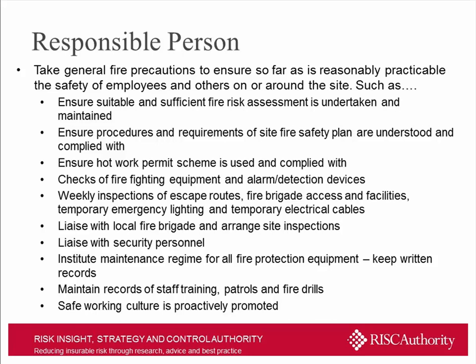One of the key outcomes of the fire that happened at Minster Court was that although the fire and rescue services arrived in very short order, with no delay in their being called and their arrival, what they found when they arrived was a fairly significant fire already, and really difficult access to any of the hydrant points that they needed, because they were within the hoarding of the building, and one or two of them were hidden beneath stocks of materials waiting to be either taken from the site or used on the site, so they had no access to a water supply.